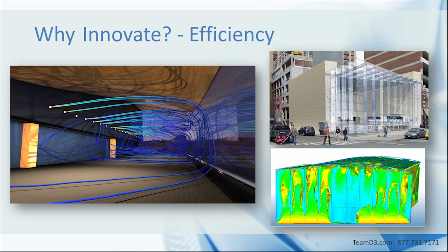Here's some specific examples of this. The BWI pedestrian connector, seen here on the left, is a long space with an unusual ceiling and shape. There's a lot of glass. CFD was used to assess the comfort within the occupied volume, which is around 6 feet above floor level. The area between the air inlet vents and the ceiling is designed to create a stratification layer and effectively act as an insulating barrier.